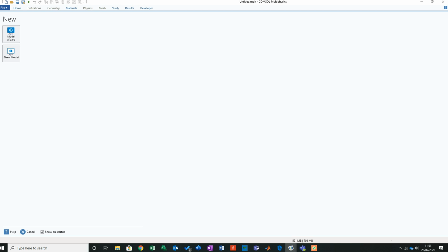area. And the assumptions that he makes and the assumptions that we will make in this are as follows really. The strains are small and within an elastic limit. Each body in this case will be considered elastic in a half space, and the surfaces are continuous and non-conforming, and all bodies in this case will be considered to be frictionless.